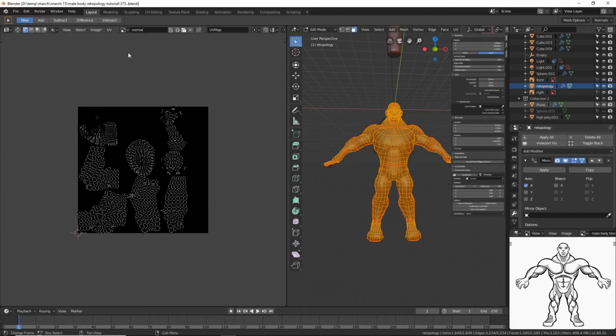Okay, what we need to do is look to our upper left, click on image. See this image, there's a little asterisk sign right there. That little asterisk sign lets us know that this image here isn't saved. In Blender, you need to save your textures externally. There's a way where you can pack them in, but for the most part, you want to save them externally.